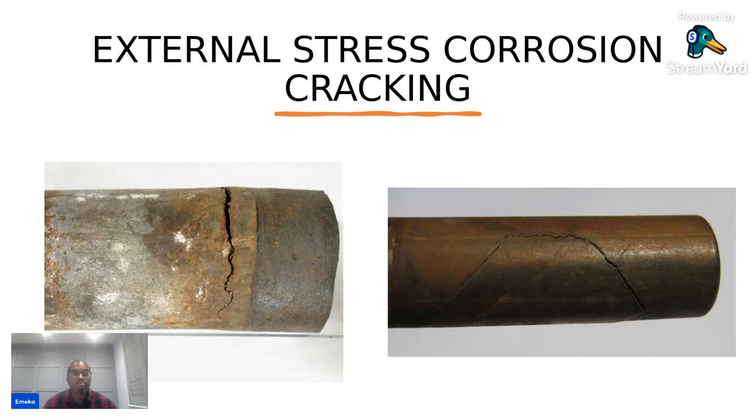These two types are related, so they are similar in a way. Chloride stress corrosion cracking affects both the internal and the external. Metal parts with severe stress corrosion cracking can appear bright and shiny while being filled with microscopic cracks.